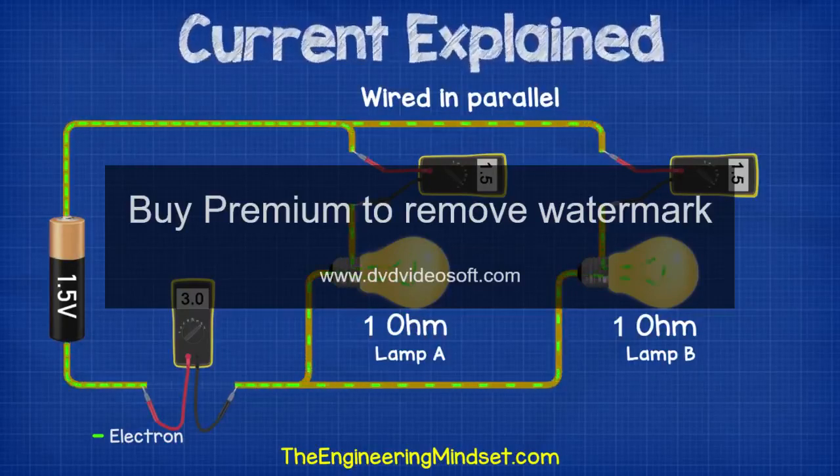But if the lamps are of different resistance, then the current is split unequally. For example, if lamp A has a resistance of 1 ohm and lamp B has a resistance of 3 ohms, then in the main wire we get an amp reading of 2 amps. In the branch for lamp A, we get 1.5 amps, and in the branch for lamp B, we get 0.5 amps.